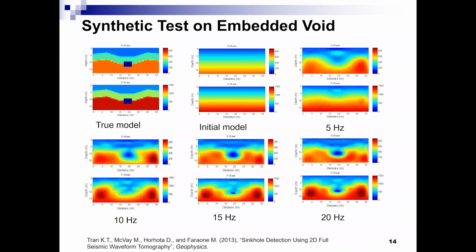Where does the initial model come from? This one we can estimate from the dispersion curve. Is that from very low frequency? Could you put 1 Hertz where you have the initial model? No, it's the surface wave dispersion curve. Just take the 2D FFT of your waveform along the multi-channel array and look at the dispersion curve. I will explain more for the real data. Right now we just accept it.